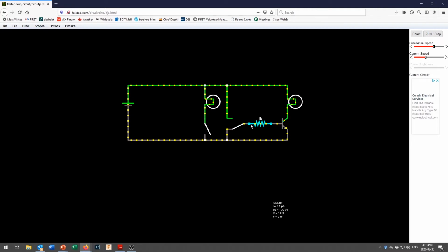So right now, I've got this switch right here tied into the ground line, so my base is not being pushed and my transistor is off. This is the same as using the digitalWrite pin, comma, LOW command, and if you were hooked up to an Arduino right here, right now you would be sending a low signal right here, and your Arduino would be telling this transistor, hey, turn off, don't let any current flow through you.